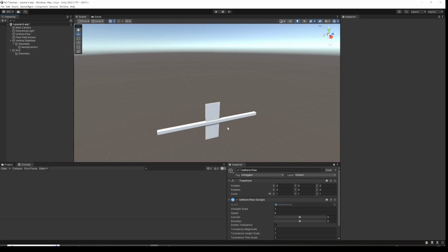But actually, in terms of our modelling strategy, most of the aerodynamic forces are going to be coming from the fin itself, or the stabilizer. So to a first approximation, we can ignore the aerodynamics of the rod. It's there for our geometry and inertia, but it's not there for the aerodynamics. So we're not going to put any aerodynamic model on that rod.